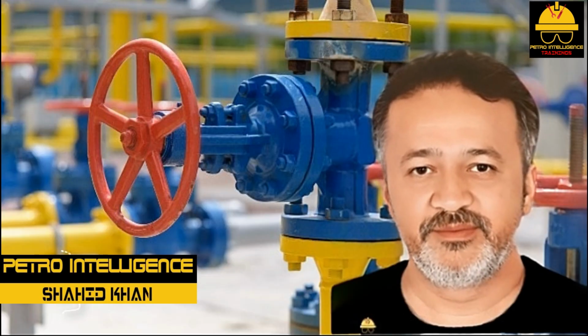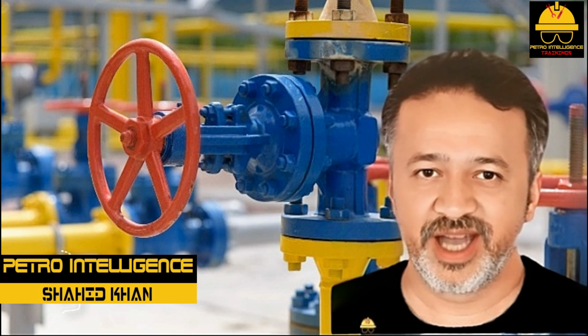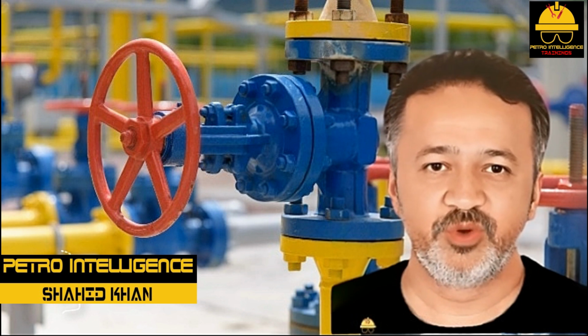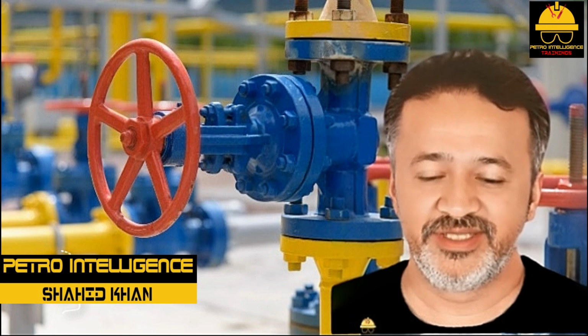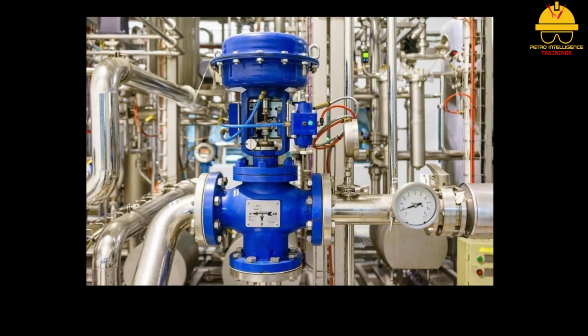Automatic valves. The chemical processing industry uses a complex network of automated instrument systems to control its processes. The smallest unit in this network is called a control loop. Control loops usually have a sensing device, a transmitter, a controller, a transducer, and an automatic valve as shown in picture. Because automatic valves can be controlled from remote locations, they are invaluable in processing.